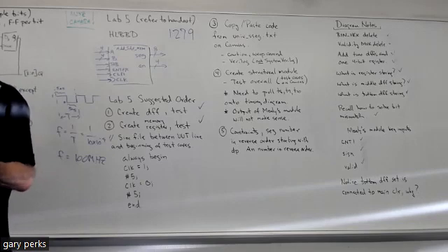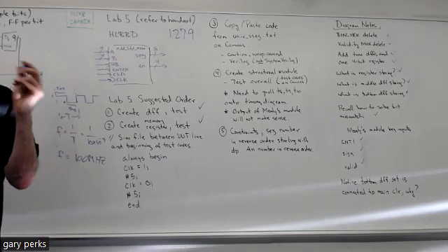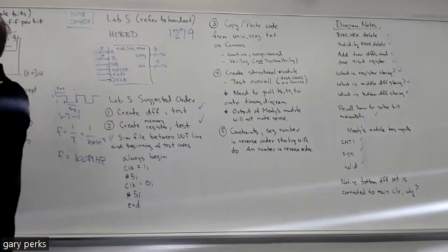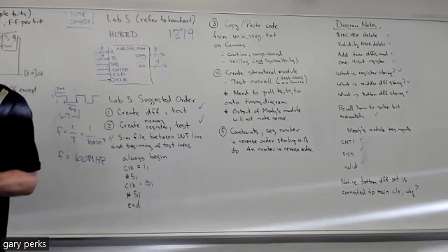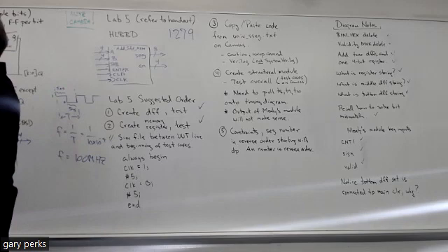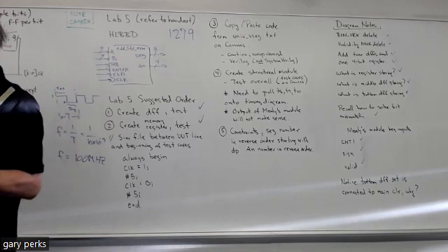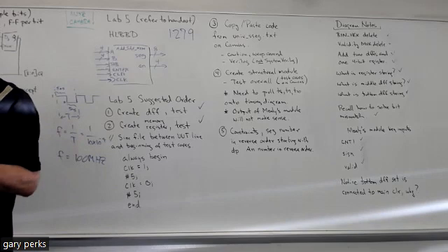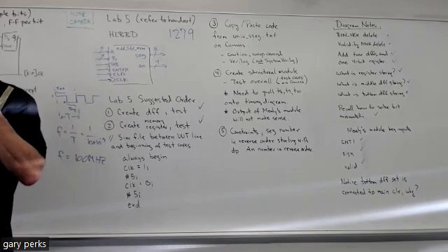And again, I can't tell you how many times I'll get emails and they'll be like, Gary, everything works, but when I hit the reset button, I get dashes instead of zeros. And it's because they connected to the clear instead of the set. Okay. Now also notice that there's these ground symbols, right? Those of you that had circuits know what the ground symbol looks like, right? And what's the voltage at ground? 0. So you just set those inputs to 0 wherever you see ground.